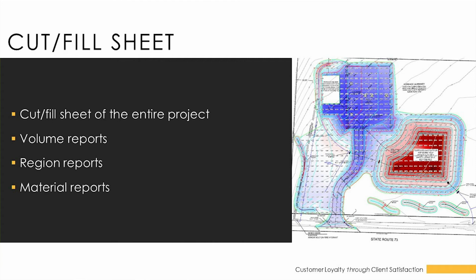Once we have that, we continue on with sort of the same process as what the estimators do. We prepare a cut fill sheet of the entire project using the CAD line work. Then we prepare a cut fill sheet set with a grid pattern set across the entire site.